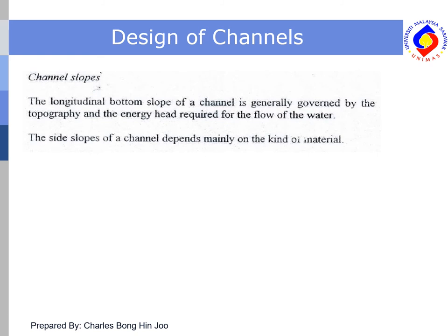For the channel slopes, the longitudinal bottom slope of a channel is generally governed by the topography and the energy head required for the flow of the water. The side slopes of a channel depend mainly on the kind of the material.